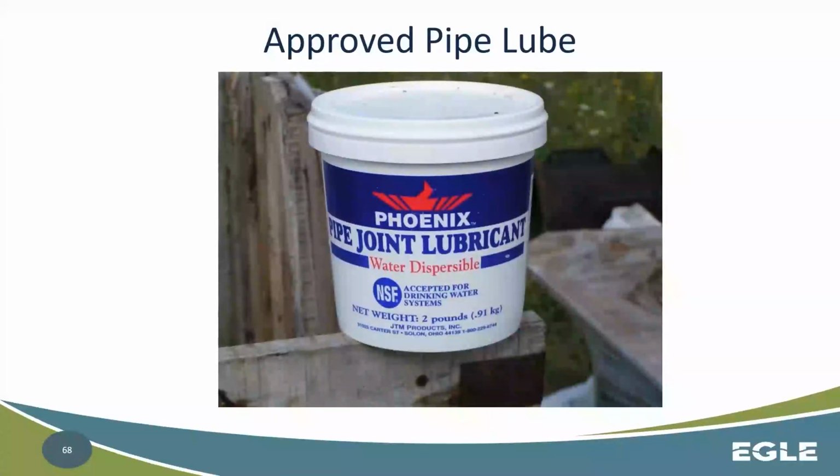Approved pipe lube, making sure that it's NSF approved. You're not using food grade things necessarily, whether it's lard or vegetable oil or Crisco or something like that, making sure that is an approved method that does not support bacteriological growth. That's again, a big one.